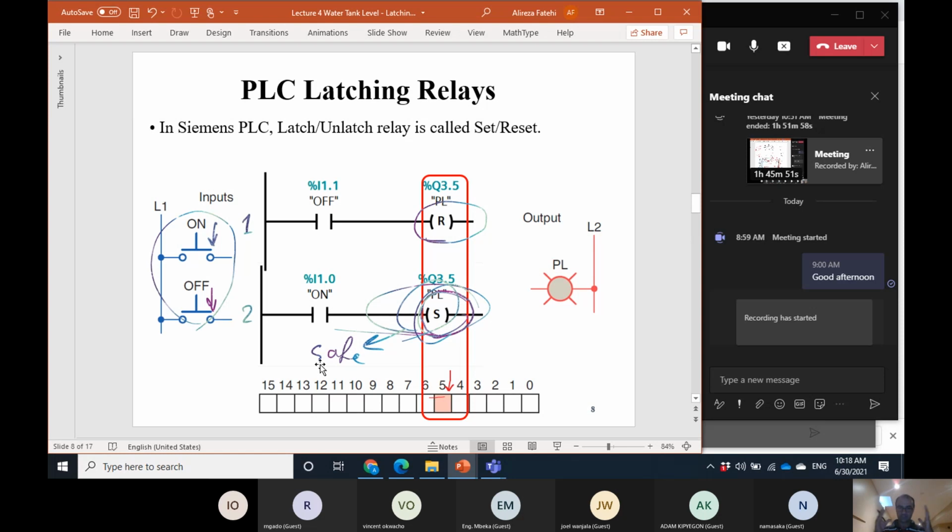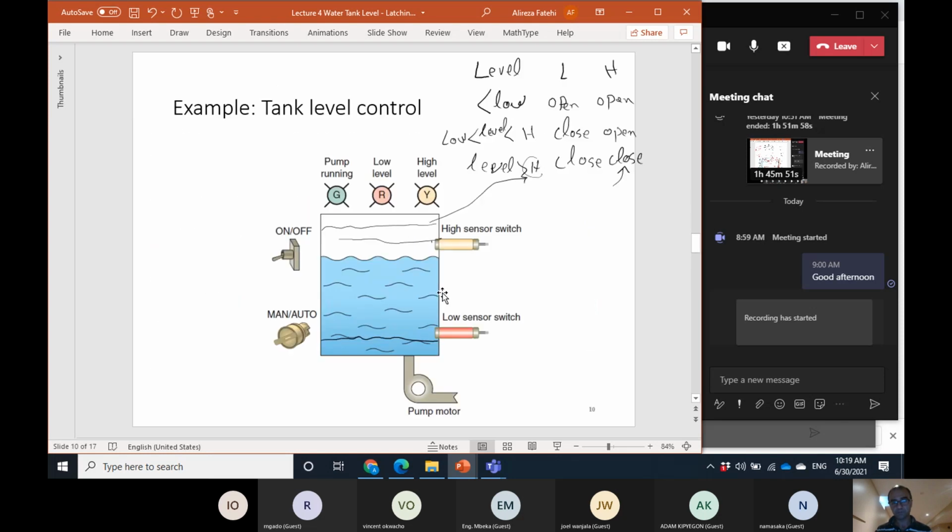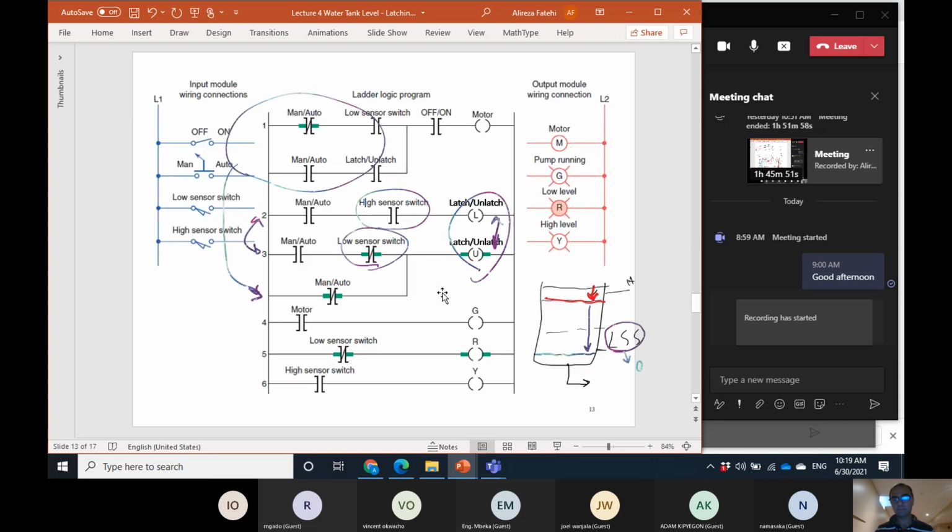For most, I don't want to say for all, please notice, but for most applications, the safe mode of the motors is to turn them off, and the safe mode for the valves is to close them. So in that case, if you have set, reset, assignment, latch for them, the safe mode should be the last one. Any more questions?